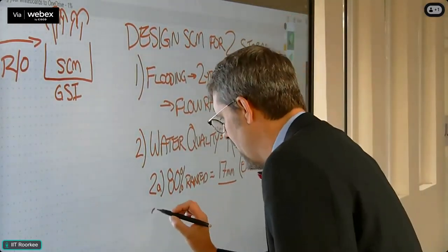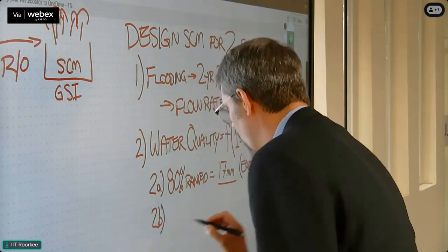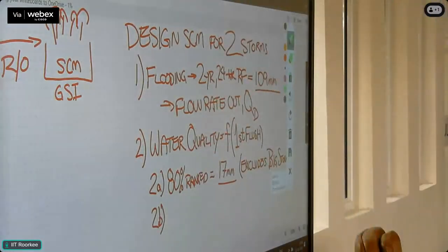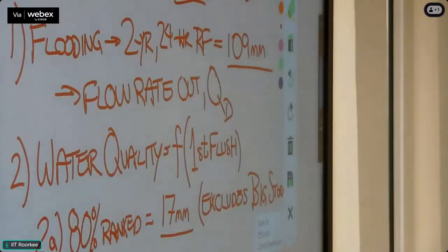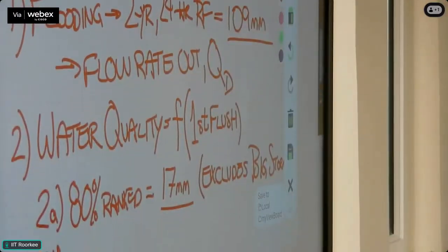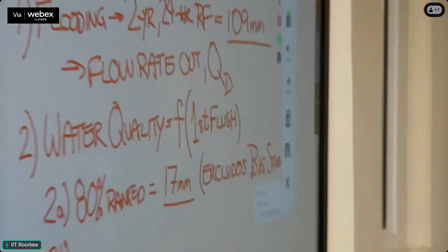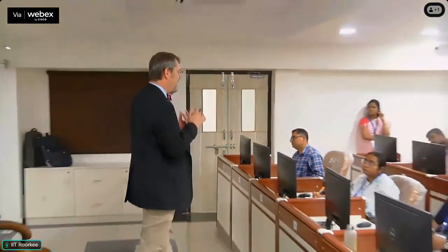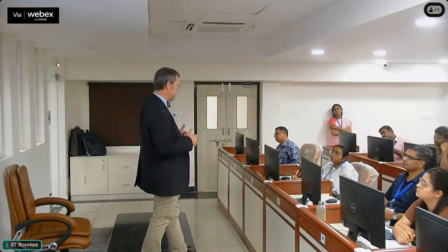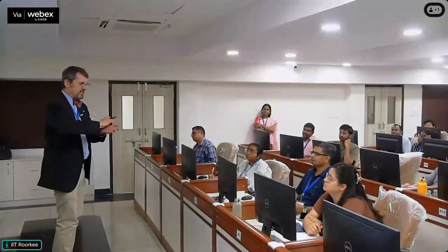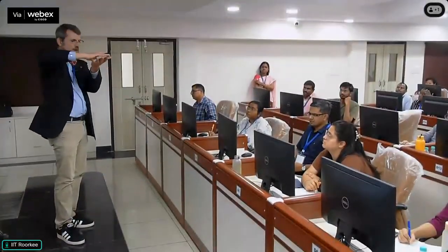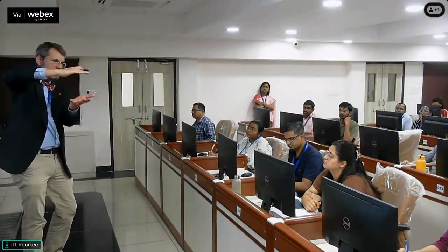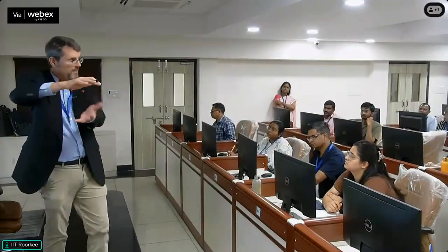So your other option for calculating a water quality event is to make sure you treat some fraction of water associated with all of the storms, all the big ones, and then 100% of all the small ones. And the way that's calculated is through integration, where you allow some fraction to bypass, but you're also capturing, even in the largest storm, some depth of rain that you want to be treated.